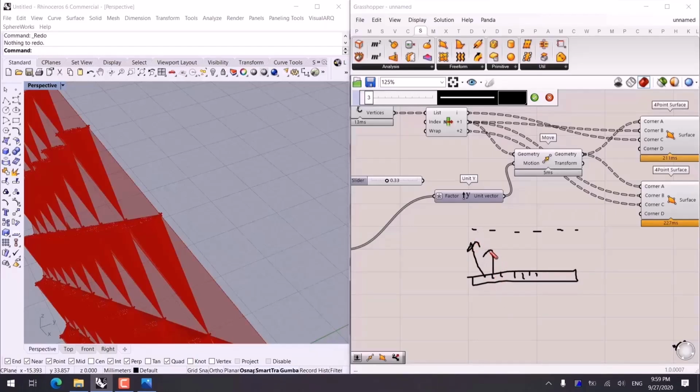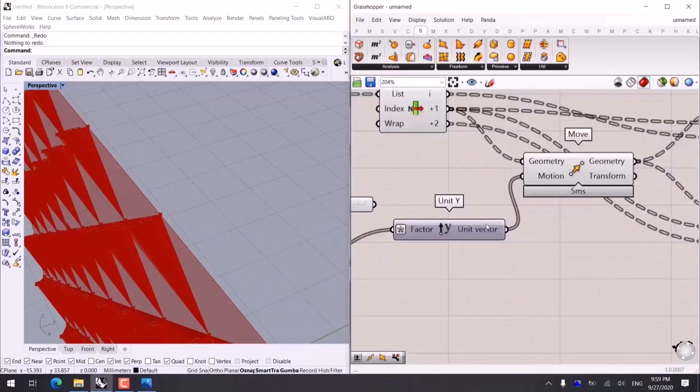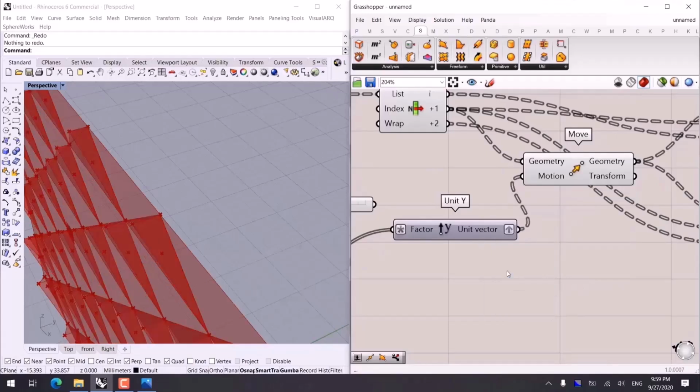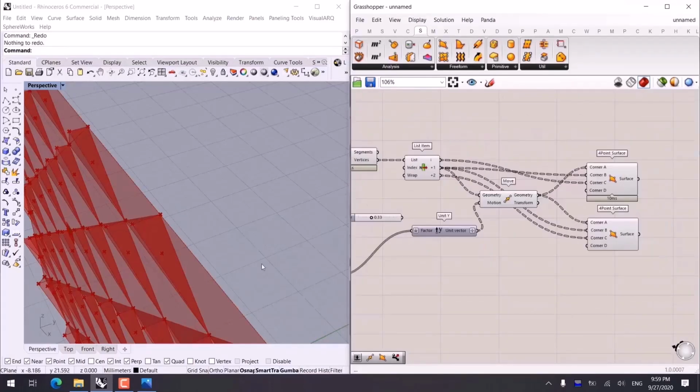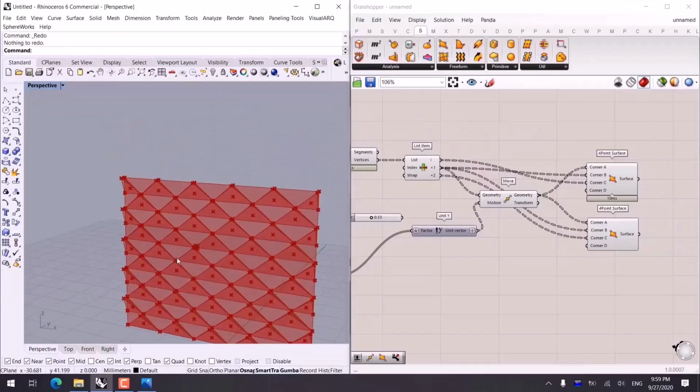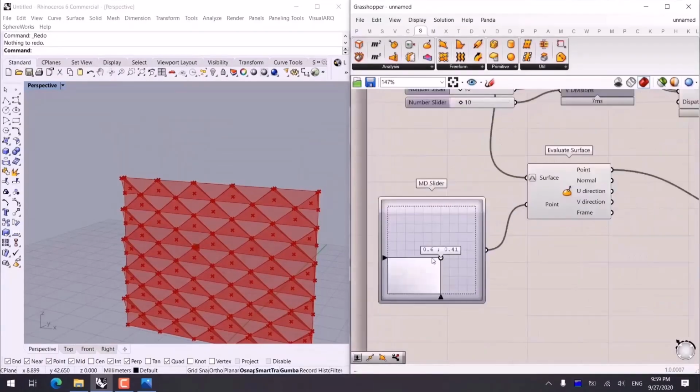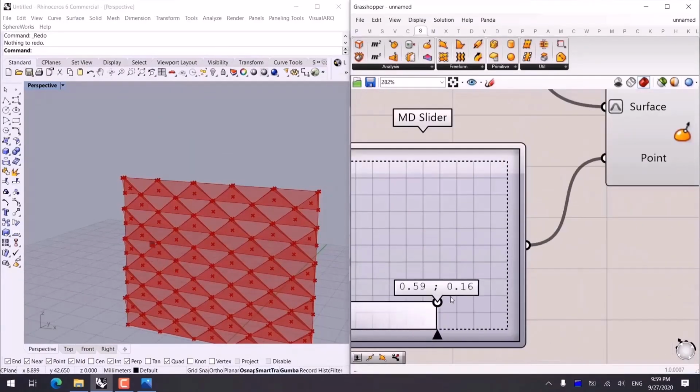Then based on the behavior of the connections, all of the items will be connected to the first branch and so on. Here the number of the branches should be equalized. So we right click and then click on graft. As you can see, the data inside this parameter is grafted. So in both we got 55 branches that are independent of each other.